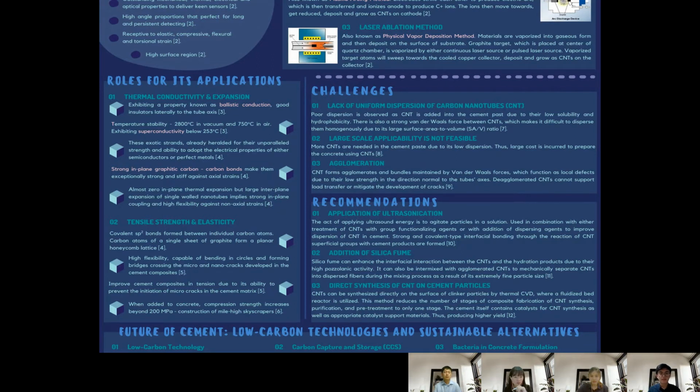This is due to their exotic strengths, already heralded for their unparalleled strength and unique ability to adopt the electrical properties of either semiconductors or perfect metals. In addition, the strong in-plane graphitic carbon-carbon bonds make them exceptionally strong and stiff against axial strains. The almost zero in-plane thermal expansion but large interplane expansion of single-wall nanotubes implies strong in-plane coupling and high flexibility against non-axial strains.